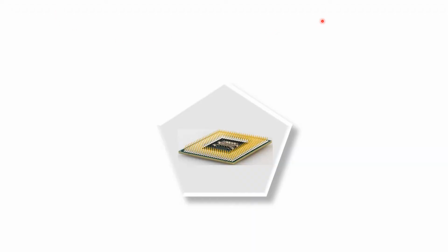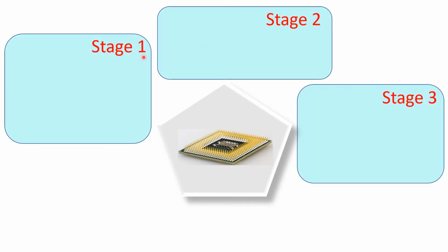Chip yield depends on many factors. Here we will discuss, for analysis purposes, 3 factors which affect chip yield. Chip overall yield is affected by the individual stage or component yield. The defective parts in each stage, either stage 1 or stage 3 for example, need to be removed to get all good pieces that meet the chip requirements. So we need to find the yield for each stage based on the defective parts of that stage. With that information, it is possible to find the chip overall yield.